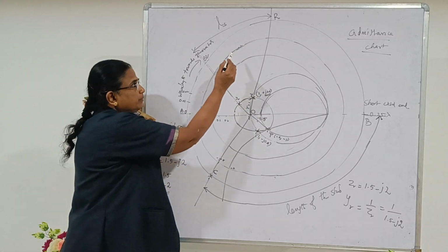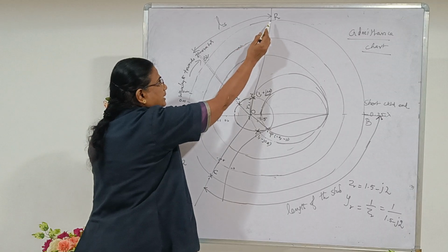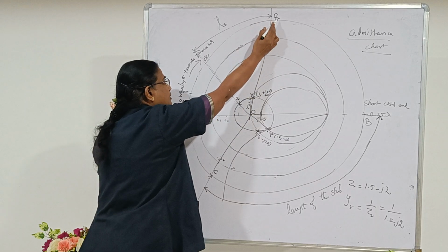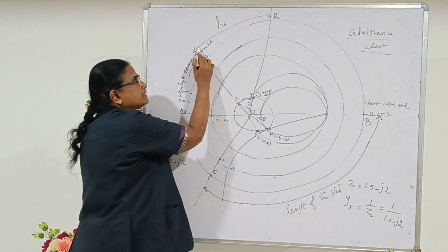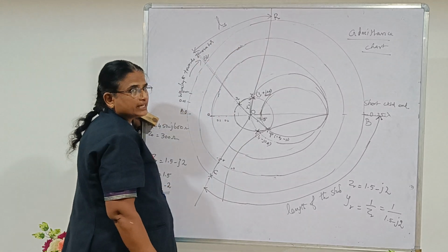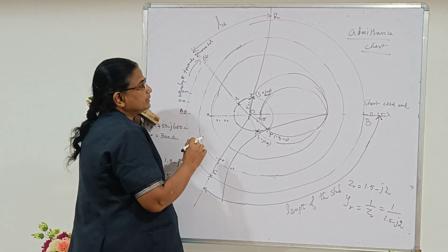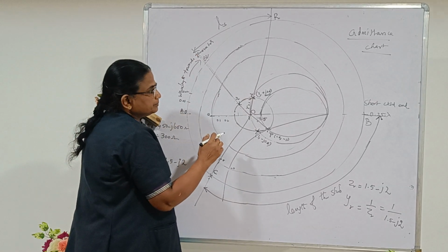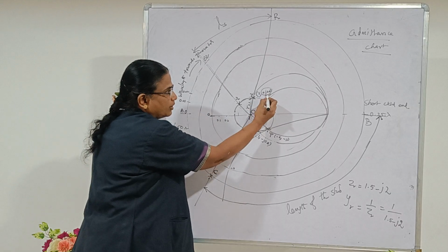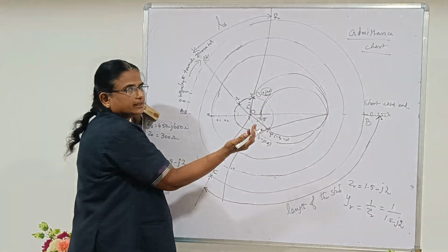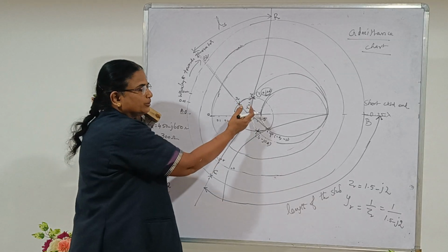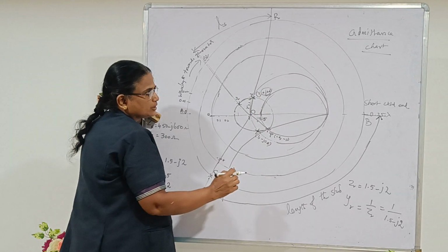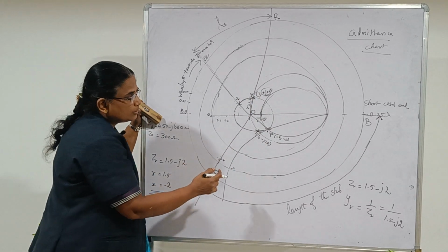So now you name this point on the wavelength scale as R. This line touches the wavelength scale. So this is R and this is Q, and this distance is now designated as the location of the stub, or position of the stub, or distance between the load and the stub. And then we need to nullify this susceptance. For example, I have written this value 0.8. It may be anything, you have to check it from the chart. So for your understanding, here I have written plus j 0.8. It may be some other value from the chart.